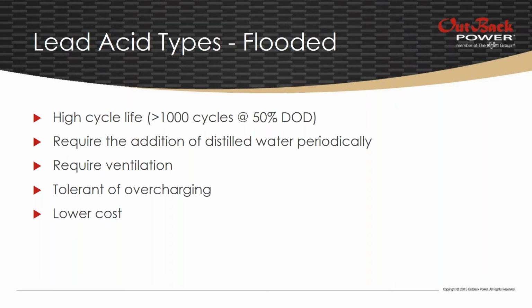Once they are in their component parts, they go from the liquid phase to the gas phase, so you're evaporating that water out of the battery. That's why you have to add liquid water periodically, and you have to ventilate the space adequately so you're removing all that explosive hydrogen and oxygen gas. Again, those go hand in hand.